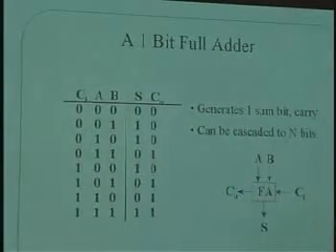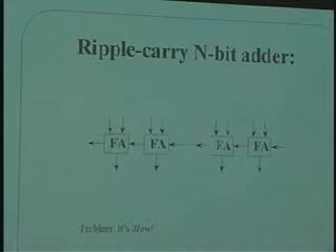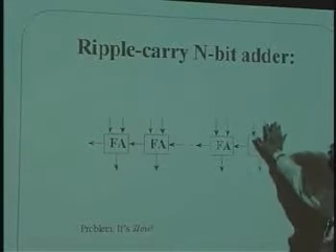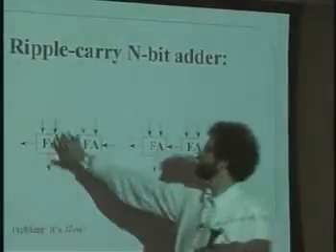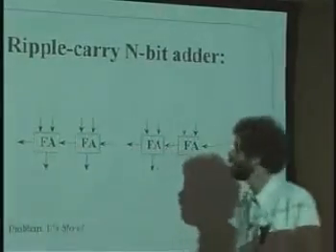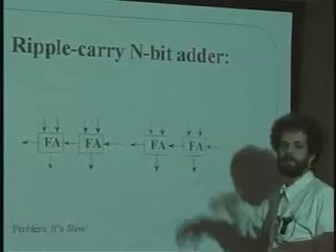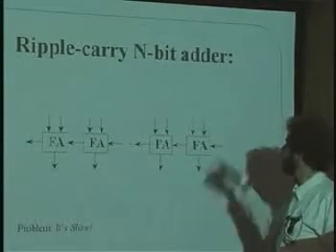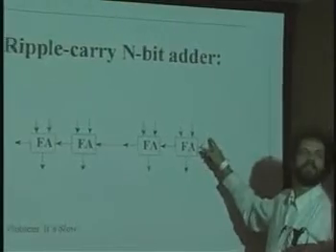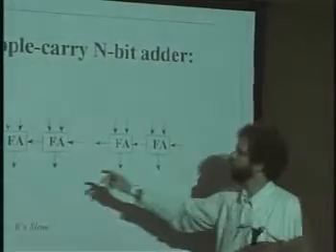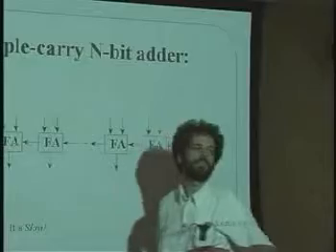Now, what you realize when you do this is that you could combine a set of full adders the same way that I just showed you there, by putting them in a chain like this, where the least significant bit is over here on the right-hand side, where we traditionally draw bit number 0, and the most significant bit is on the left-hand side over here. And if we're just summing together two n-bit strings, what carry-in do you think we should feed in on the right-hand side here? A 0 or a 1? 0. Okay, great.